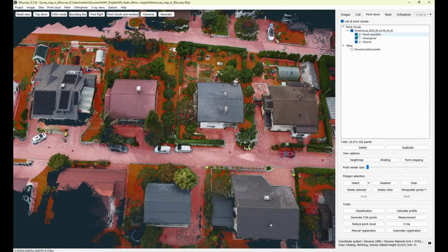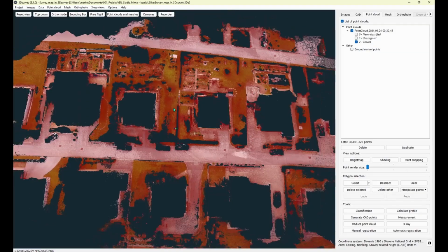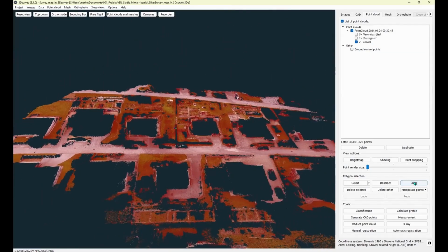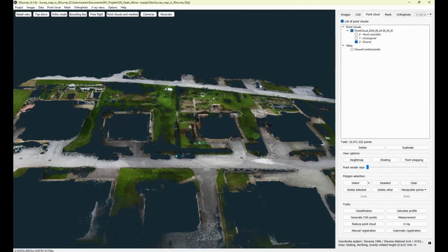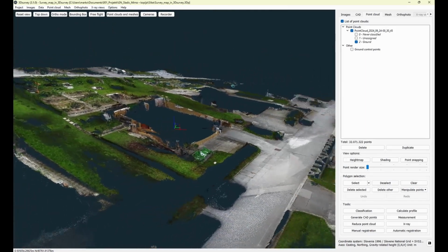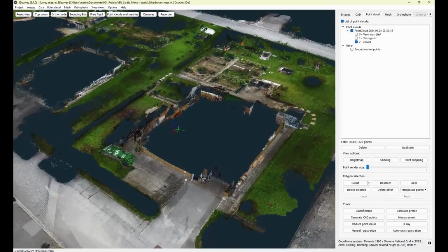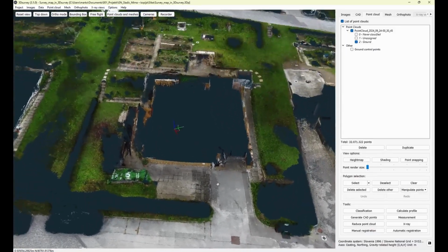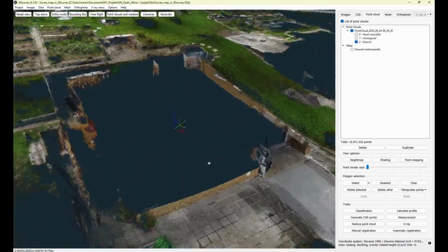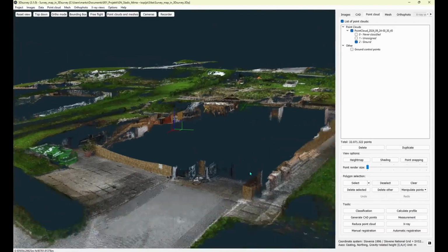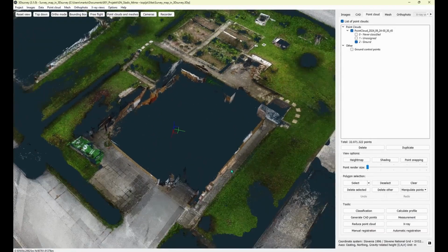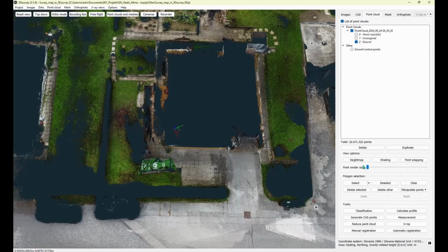enough. Okay, if I now deselect never classified and unassigned class, which I got with the classification, and I click on clear to get my natural color back, I can see my terrain classification here really nicely. Okay, what could be maybe better? I still have a bit of the house, which I would love to remove or put to another class.